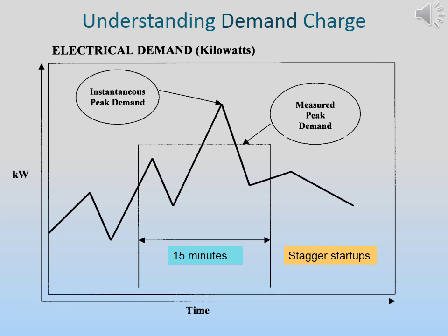One suggestion is to think about staggering equipment operations. It may be possible to save money here without the need to do a payback analysis. We have big energy users, and if we can stagger the starting of this equipment, we can save energy. We are not saying start this at this minute or start that one the next minute. That is not going to do anything for us. It has to be greater than our 15-minute period of time we're talking about here.